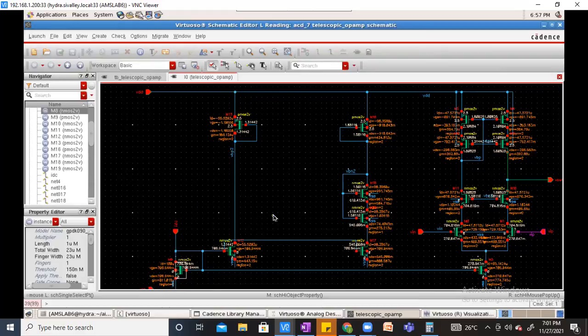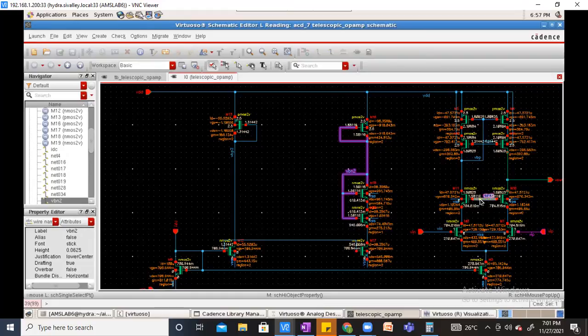Yes. Great. So now coming to this part. I have to generate this now. So how much minimum voltage do I want here? 1 overdrive and 2 overdrive and 1 VGS. Essentially 1 overdrive, 2 overdrive, 3 overdrive plus 1 VT. So how to do that? This will be giving one overdrive for me. This is the second overdrive. This is the third overdrive plus 1 VT, with this connected configuration. So that's what I'm generating here.